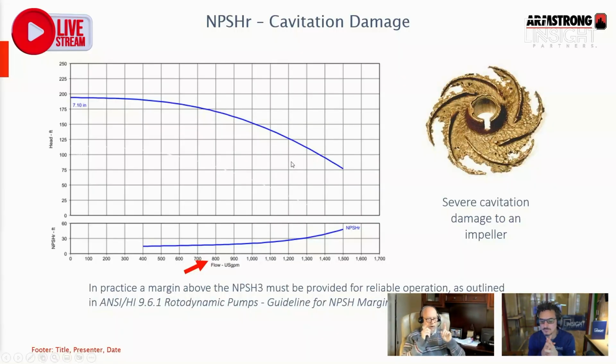Understand, when you take pressure readings across your pump, use one gauge. Don't use two different gauges. Because if the gauge is wrong, if the gauge reads 10 pounds high, it's going to read 10 pounds high when I read it on both sides of the pump. Right. But if I got one gauge reading 10 pounds high and one gauge reading 10 pounds low, I just added a whole bunch of error to my reading. If I use the same gauge for both readings, even if the gauge is wrong, my differential is still correct. The difference between the two readings is still the difference. Okay. Mathematically, it's still the same number.